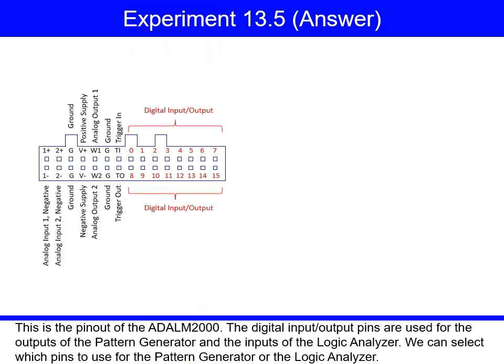This is the pinout of the ADALM2000. The digital input-output pins are used for the outputs of the pattern generator and the inputs of the logic analyzer. We can select which pins to use for the pattern generator or the logic analyzer.